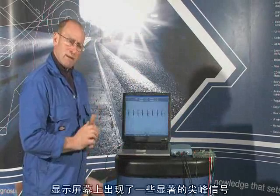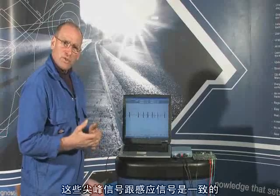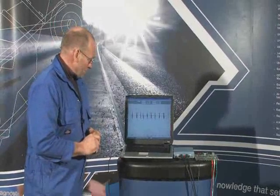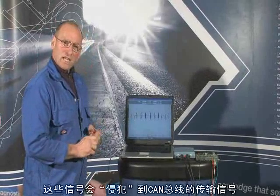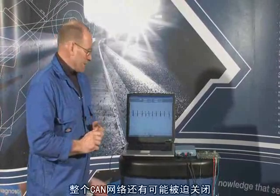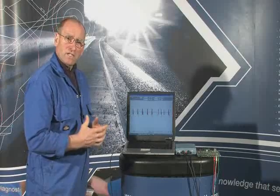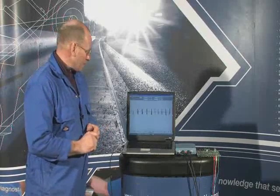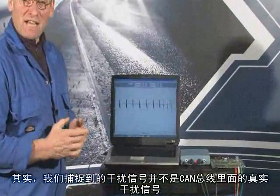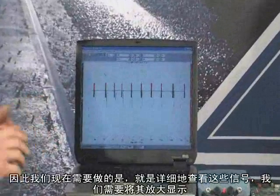These additional spikes that now appear on the screen are high frequency induced errors, or simulated high frequency induced errors, that would cause corruption and chaos to the CAN messages, would cause rejection of messages and the possibility that the entire network would shut down because it can't understand the messages that are being transmitted, with potentially catastrophic effects within that particular network.